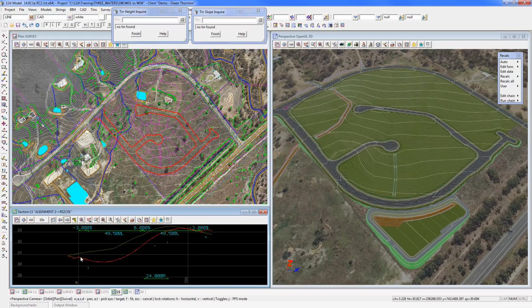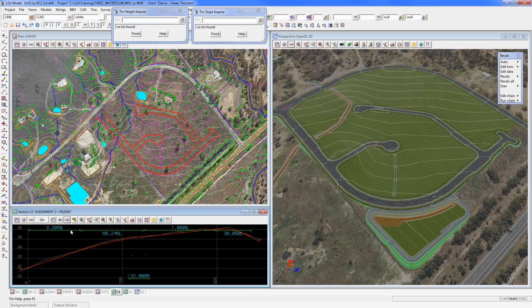And then we also have road C, which is this little side road here, and it's got a cul-de-sac at the top with a sag and a crest, and then another sag at the bottom just before the intersection with road B. And so we'll just make a mental note that there's a sag there. And road D, again, there is a sag and a crest up in the cul-de-sac bulb here, and it basically grades from the crest all the way down to the intersection with road B. So that's what we've got to work with.